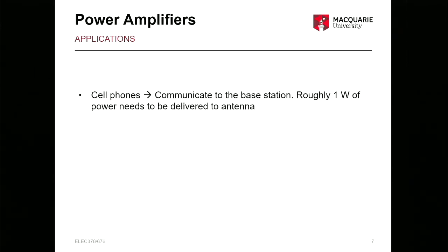So first, what kind of applications do we use power amps in? So of course now you've already done mixers, you've done differential amps. Most of this is using still low current, low power technology. At some point you need to have an output stage that drives some real world application. So a common requirement for power amps would be cell phones. So you need to communicate to a base station. You need significant power to do that, okay? Typically around a watt delivered to the antenna. So you need a power amp there.